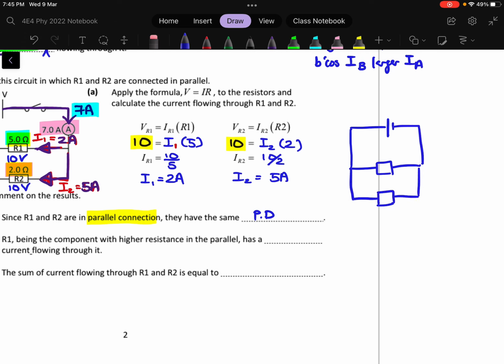provide you with one. Let's say there's a charge coming out from the battery. Between the battery and this point there is no component, so it will still have 9 volt. Extending from this logic, this point will also have 9 volt because there's nothing in between them. Then down here it should also be 9 volt, because there's nothing between them. Same thing, extending from that logic, down here it will still be 9 volt.